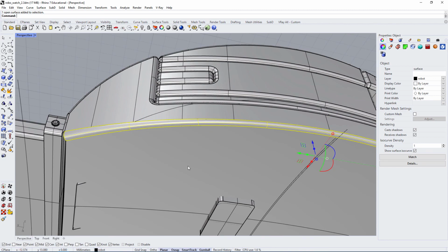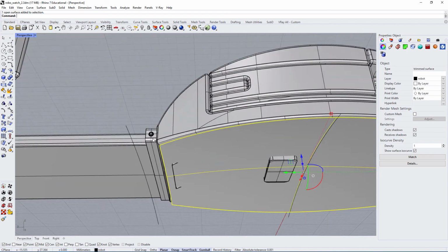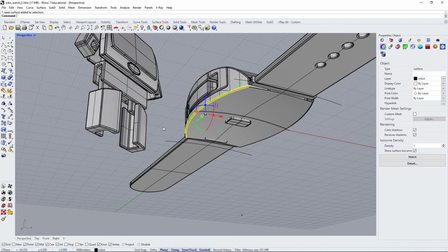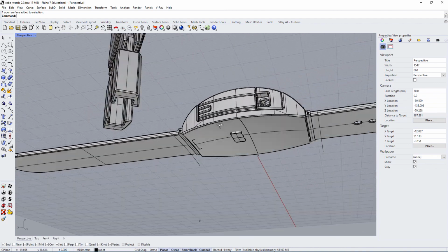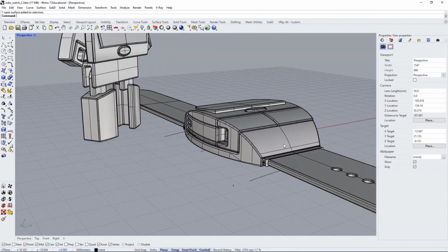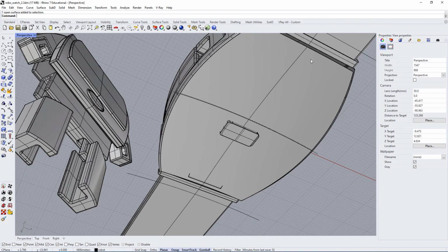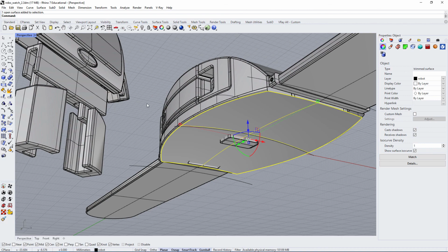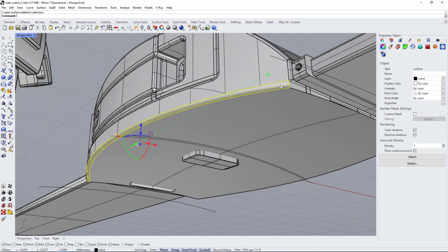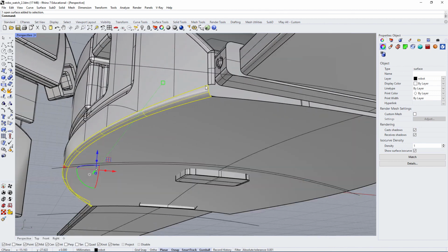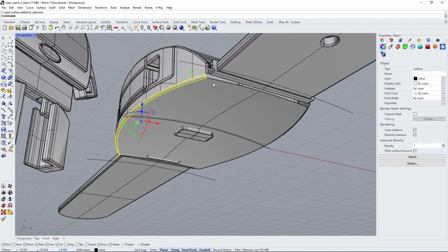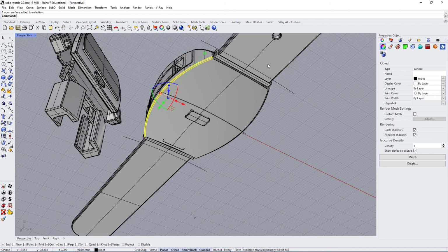So that's how you would create a complex major surface and a complex transitional surface, which gives us this compound surface that we're looking for specifically for this assignment. And that's what I would suggest you do if you don't have enough surface complexity, and for your assignment, if you're asked to create more surface complexity, this is the way to do it. Just add some double curved surfaces to something that's flat, and then redo your transitional surfaces wherever they're needed. Make sure you have a nice four-sided corner surface, and that's it. Yeah. So I hope this makes sense, and if you have any questions, just let me know.